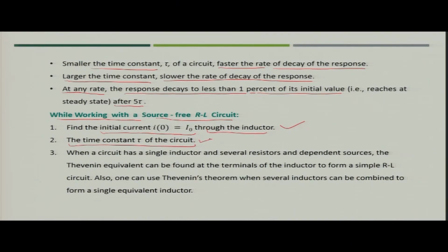And third, the important thing is that when the circuit has a single inductor and there are several resistors connected, or there may be some dependent sources also, the Thevenin equivalent would be a good option to analyze the circuit.